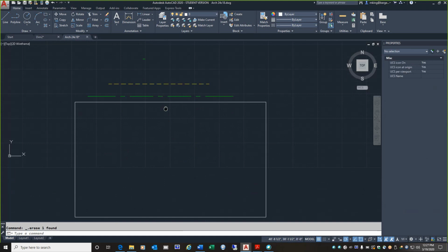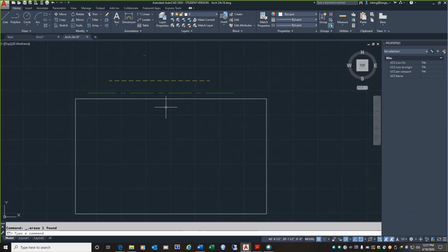right way. This is creating an architectural dimension style that is proportionately scaled to the dimension of this drawing. And to know that, we have to remember that when we created this drawing, we did this based upon a 1/4 inch to the foot on an 18 by 24 sheet. So 1/4 inch to the foot, that's important.